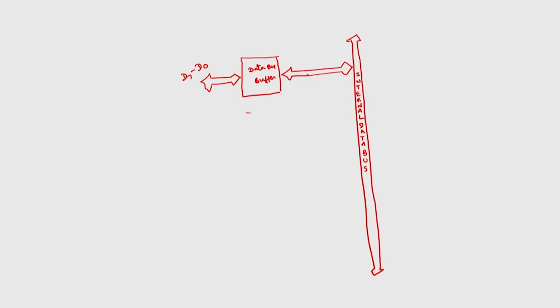Then we have read write control logic. This is also bidirectional. Some control signals are input signals, some are output signals, because it can read or write memory as well as IO. Then what are the different signals? The very first signal for any read write control will be chip select bar. You first have to select this chip using some address decoding logic.